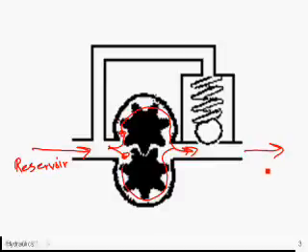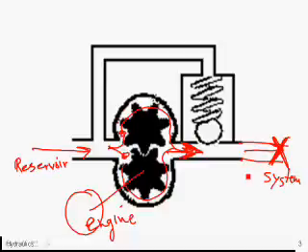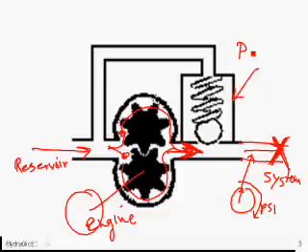Now let's say the fluid's going to the actuators, but let's say that we've turned off the selector valve, so no fluid can go in here. If this engine-driven pump is driven off of the engine, and the engine doesn't stop spinning, and this pump doesn't stop spinning, we're going to continue to push fluid out here to the actuators into the hydraulic system. So the pressure in here, the PSI, would go up and up and up, and finally something would burst, something would break. So we don't want that pressure to go too high, so we're going to have a pressure regulating valve.